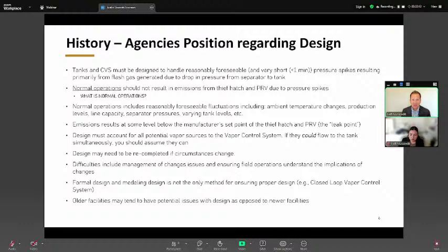And so in many instances, we look at our first pass being kind of the 100-year flood, the worst case scenario, and then we chip away at that to find operational optimization of how to run these facilities. So sometimes we'll put multiple analyses together. So we put together, okay, worst case scenario, all of our vapor flashes going through tanks at one time, and then we also look at a reasonable operational case that we don't submit to EPA, but we use it for operational focus.